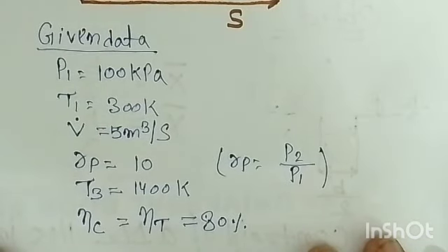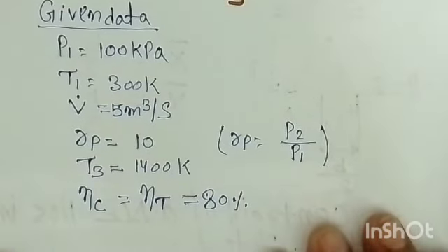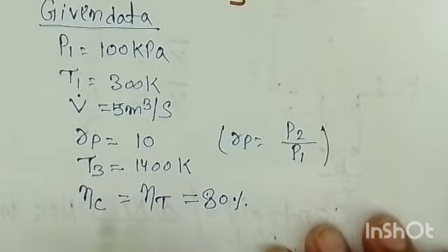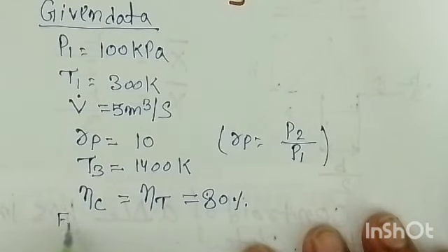right? Then the fluid which enters the compressor is air, right? So air properties we will take. That means, the specific heat at constant pressure of air is 1.005 kilojoule per kg Kelvin, and the adiabatic constant, which is gamma, we will take as 1.4. So you can additionally write, that is not given in the question. So you need to remember that for air,